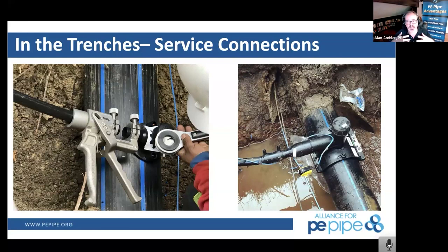One of the things about a non-corrosive system, such as HDPE pipe, is that if we put a metallic fitting on there in corrosive soils, then that metallic fitting becomes our sacrificial corrosion location. That's basically where the electrolysis, for lack of a better word, the movement of energy within that soil, is going to focus on that mechanical piece.